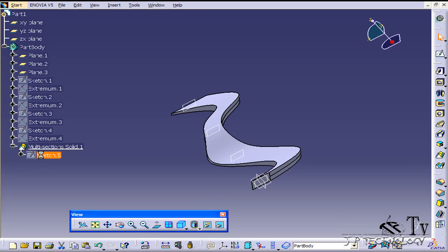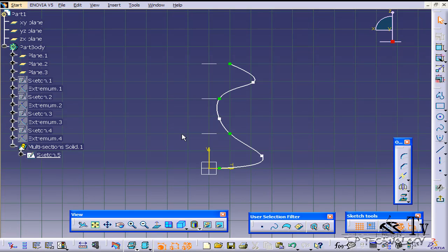Now I'm going to go back into this sketch, and what I'm going to tell you is that when you're doing these, especially with something like a square, you need to find a common edge or common point that you're going to whip everything around with. So what I did here is I always use the right edge point on top. So using that, you're always using that edge to move it around. If I was to use, say, the left edge point and move them around, it might be too dramatic of a curve and turn, so it might fold on itself and the part might not come together at all. If you did a circle, you'd probably choose the center point of each one and whip it around from the center points.